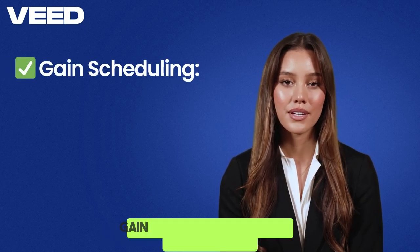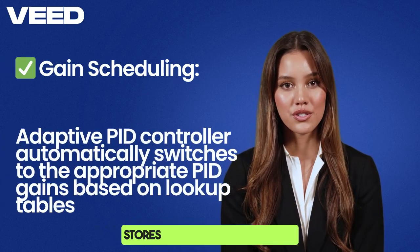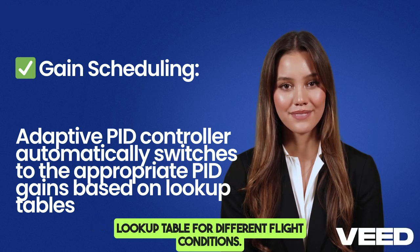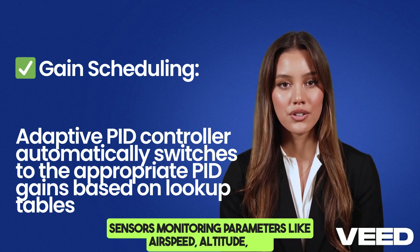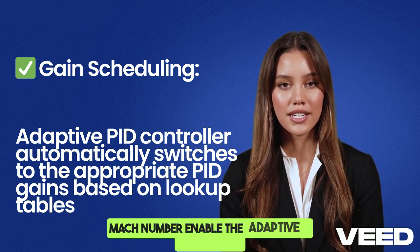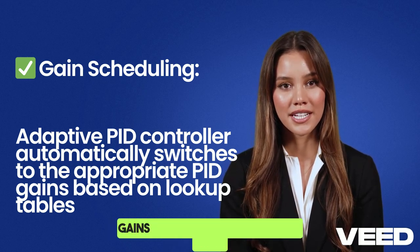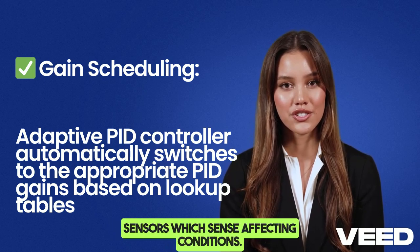1. Gain scheduling. The aircraft control system stores predefined PID gains in a lookup table for different flight conditions. Sensors monitoring parameters like airspeed, altitude, and Mach number enable the adaptive PID controller to automatically switch to the appropriate PID gains based on lookup tables of these sensors, which sense affecting conditions.